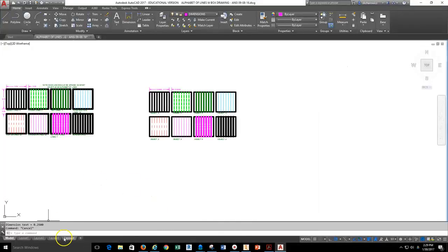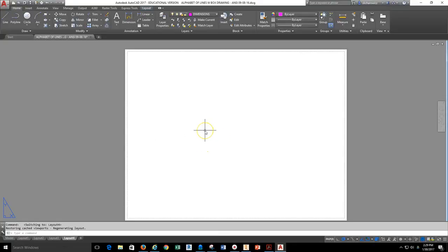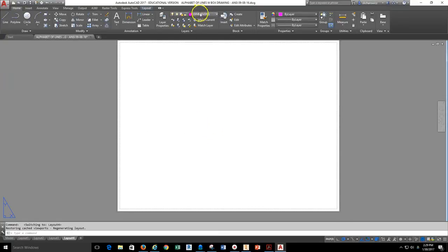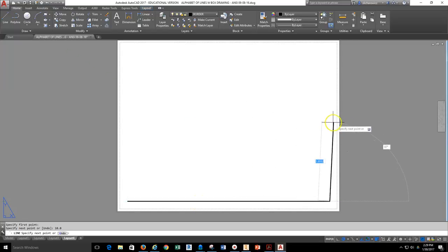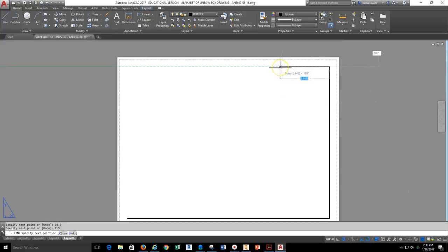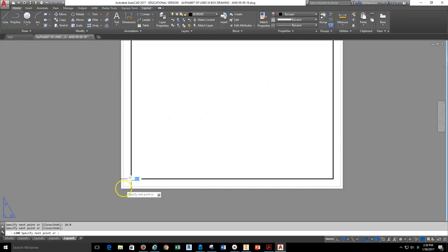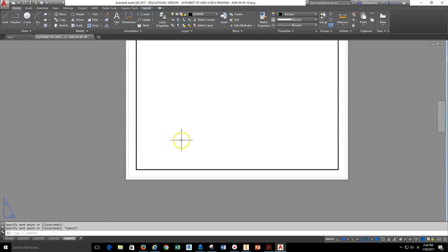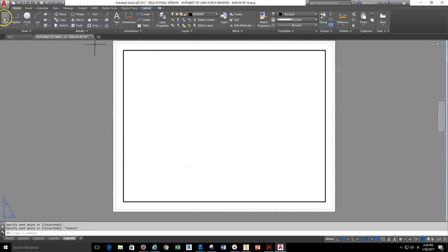So if I go to AutoCAD and select a blank layout, I can then go ahead and select my border line, as my border line is the layer that I will create for my title block, and then I just start drawing in the title block. Title block should be centered approximately within these dashed lines, as those hidden lines here, or I should say these dashed lines are the printable margins of the paper, and then you just start drawing directly on this paper for your title block.